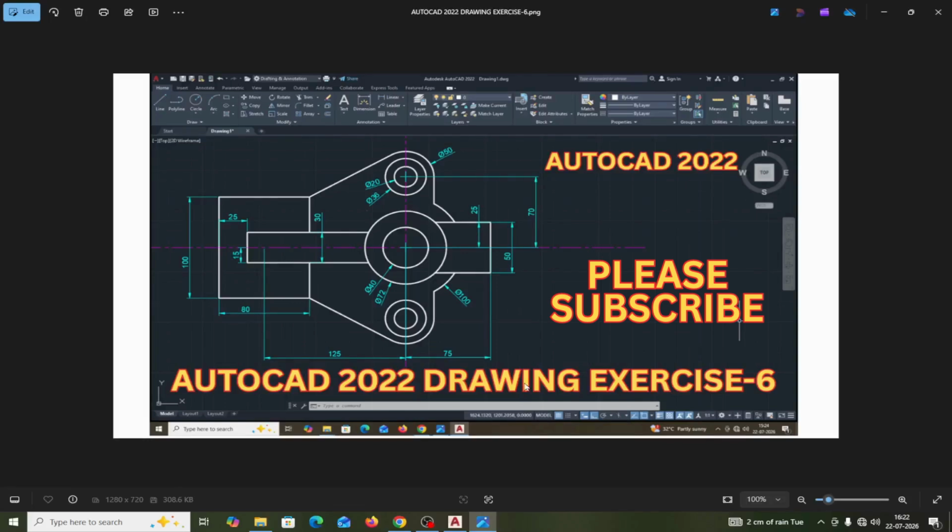Hello everyone, in this exercise of AutoCAD, I will create this drawing. I will start from this rectangle, this 100 by 80 rectangle. Actually, I will make the upper half portion. Then I will mirror it. First, I will make this rectangle 100 by 80, and from the center of this rectangle, I will make